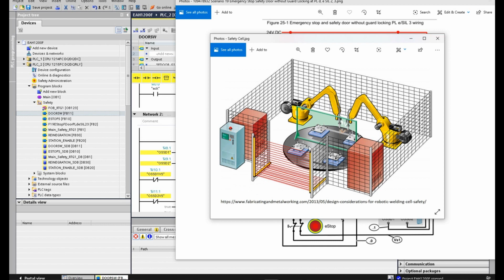Meantime, the other side has already turned towards the operator, and at that time the operator can load the part at the other side. So as we can see, because the operator needs to work at this area, and at this area we have a turntable and the tooling system towards the operator side, we do need a light curtain to protect the safety of the operator. So usually we will mount the vertical and the horizontal light curtains at this area.